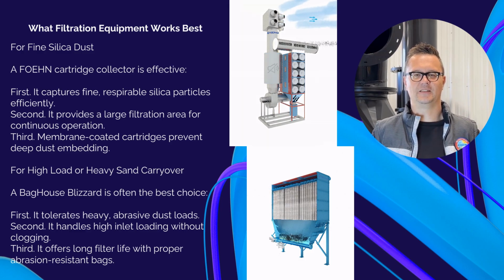Abrasion protection. Sand dust requires special design features. First, abrasion-resistant duct elbows. Second, inlet baffles to reduce direct filter impact. Third, ceramic or hardened steel liners in high wear zones. Fourth, pre-separation cyclones when load is extremely heavy.